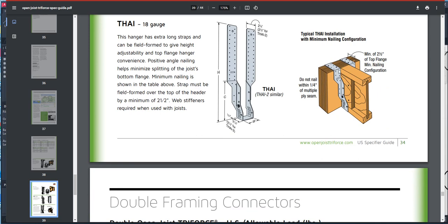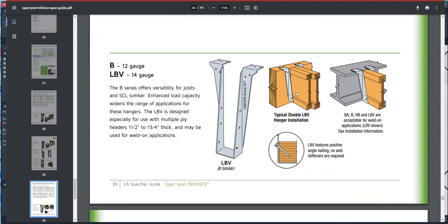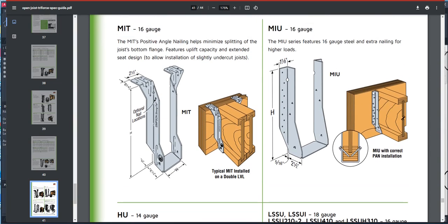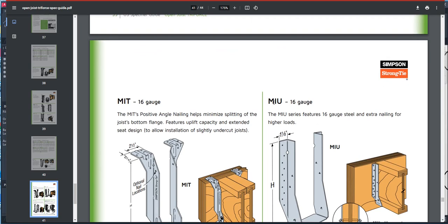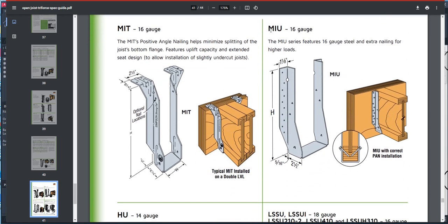What you really have to do is make a little notch on top of the beam, so this one is flush with the surface. And this one's for the I-beam. This is something that we can use, but this is for double. In reality, we really want something like this. It doesn't go over the beam. There's certainly a height that we need, and this is a Simpson Strong-Tie MIU system. So once you have located the correct connector, you may want to look at the Simpson MIU system.